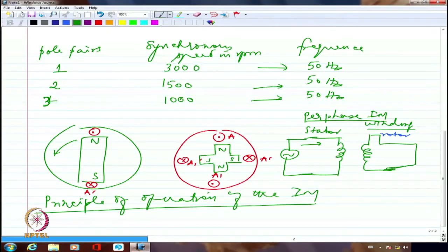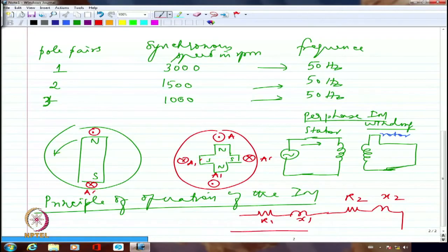You remember the equivalent circuit of the transformer where we drew that this is R1, this is X1. X1 was leakage and I had R2 and X2 was leakage, clearly. And I had the entire thing connected. I'm not even worried about the parallel parameters. I have short circuited, so I'm not really unduly worried about it. So I'm going to apply V1 here. This is what we wrote as the transformer equivalent circuit, of course with R2 dash, X2 dash.